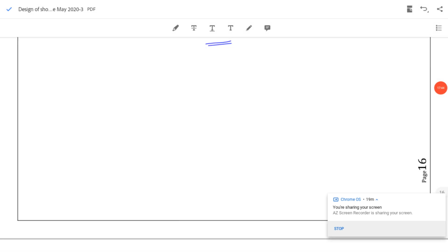Now, in today's lecture we have studied how to design a single shoe brake. We can find the value of Fn, that is the normal force. Ft is the tangential force. Ft is related to Fn by Ft equals mu Fn. Whenever the angle of contact is greater than 60 degrees, I have to replace mu by mu dash. Now we consider anti-clockwise rotation of the drum also.